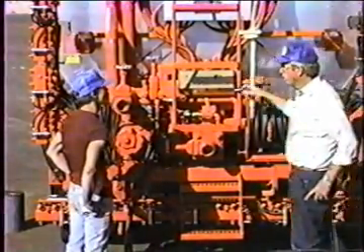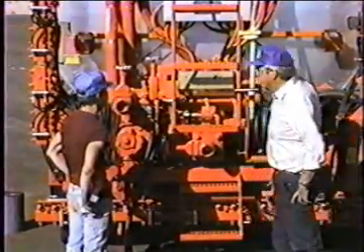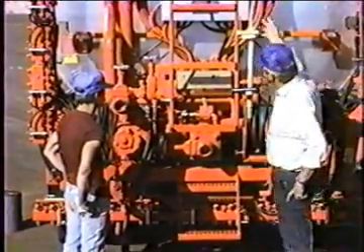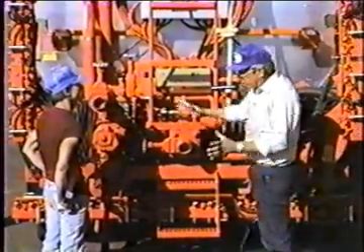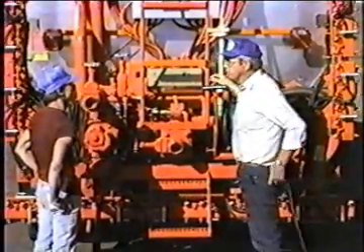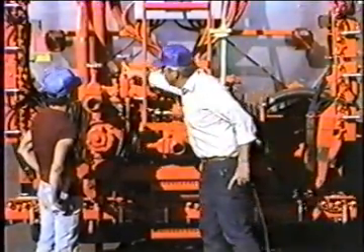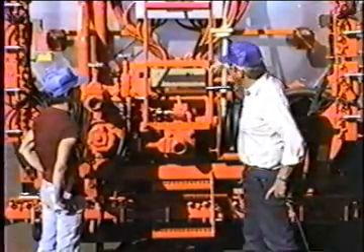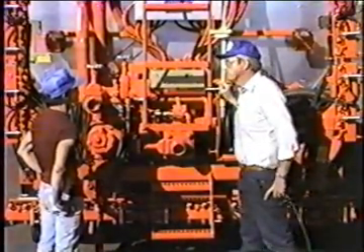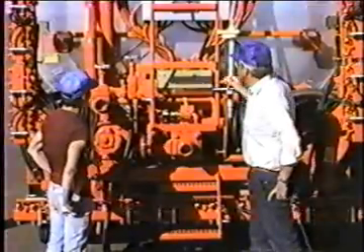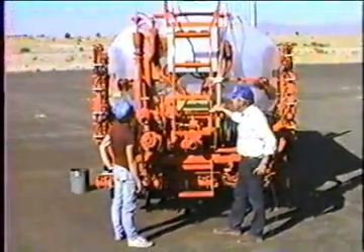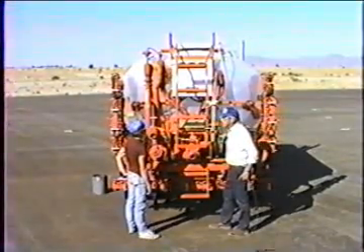When you turn it on, everything that is pumping is going to come out through this hose. Then, if you're getting too much pressure, that is, if it's spraying out too hard, you've got two choices. Either crack this valve slightly to relieve some of that pressure and let some go back to the bar, or slow the pump down a little bit. Go to the cab and slow it down a little. Do your handwork. When you get to the end of your handwork, you want to clean out the hand hose.